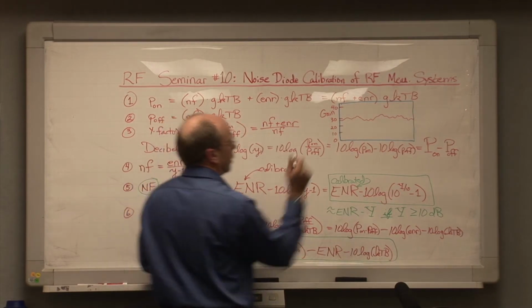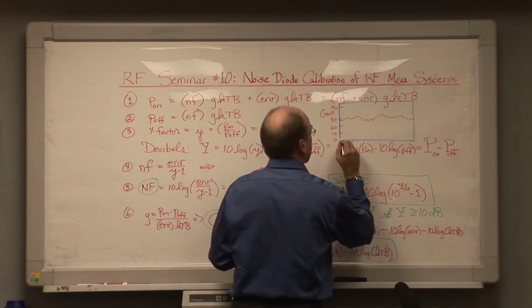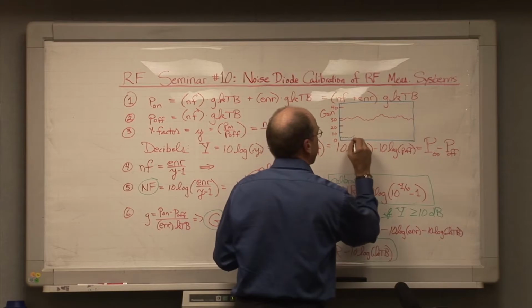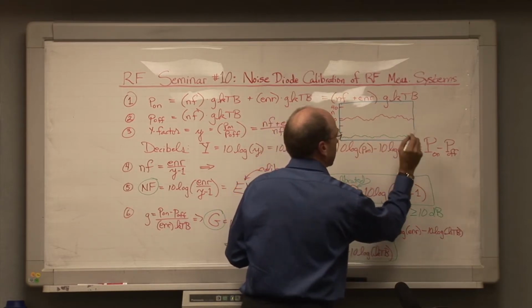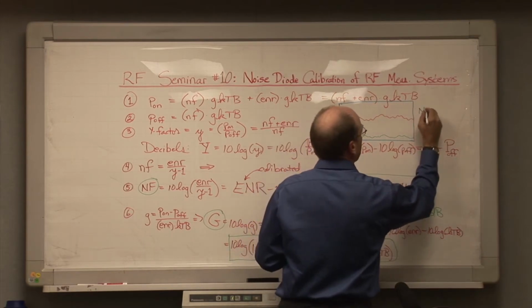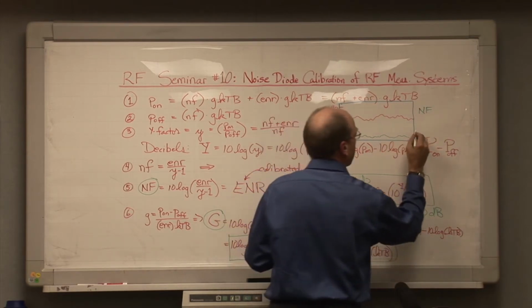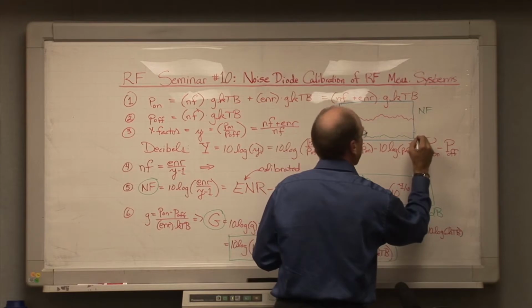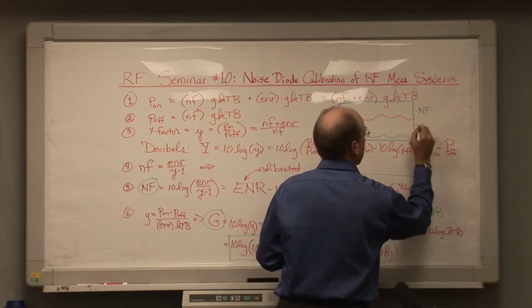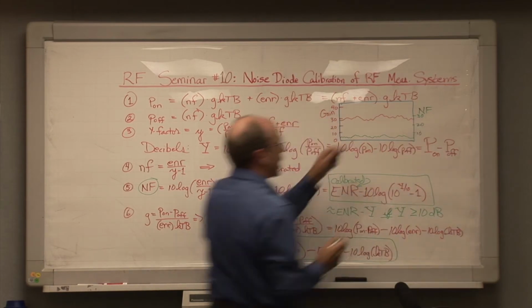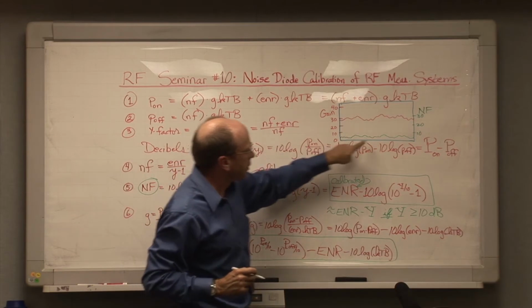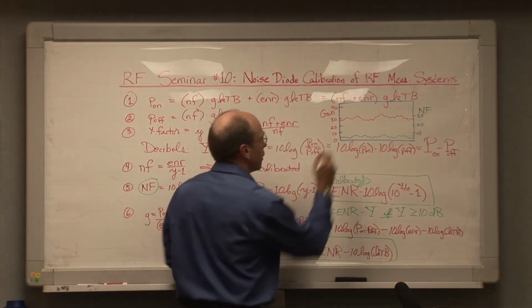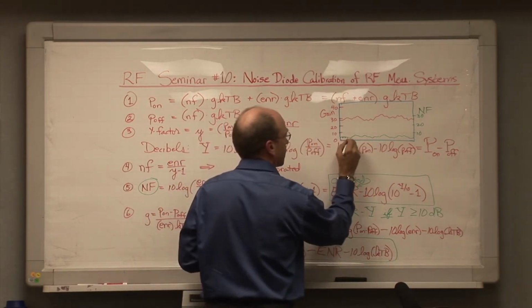And then we can graph noise figure in a different color. We'll assume that we have a noise figure of a few dB floating along something like this down here. And we'll graph that over on this axis, and now this might be something like 10, 20, 30 dB and so forth of noise figure on this axis. So it's easy to produce a graph that shows both the gain and the noise figure as a function of frequency across the measurement range, where what we've actually done is do this computation for a lot of individual points running across.